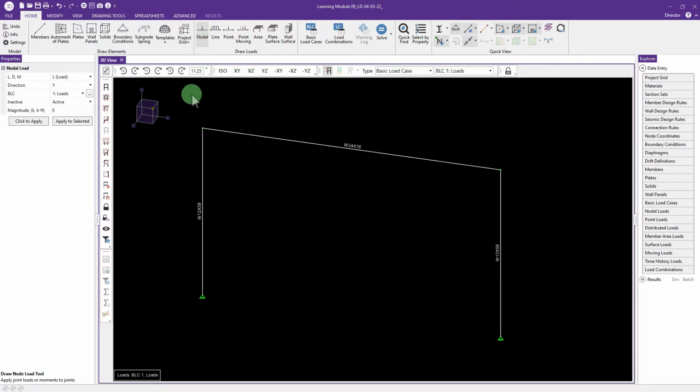You'll see from that learning module, they want us to start off with case 1, I believe, and case 1 has an ultimate vertical load of 130 kips and a lateral load of 13 kips. All right, 10% of the vertical in this instance. And it actually wants us to model some imperfections. So they want us to model the geometric out of plumbness imperfection directly in the analysis. Let's go ahead and put in the loads.